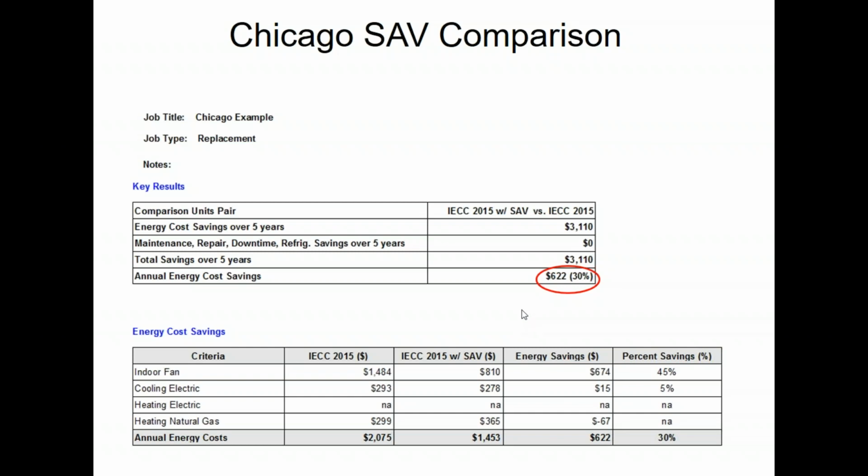So you can see how impactful saving fan energy is and why that's getting picked on in the energy codes now. So you're going to see more and more of that. Right now at TEC, our default stock unit is a staged air volume unit. There's certain sizes we don't do that, but for the most part, 90% of what we're quoting you is going to have a 2-speed fan on it for the past 2 years.